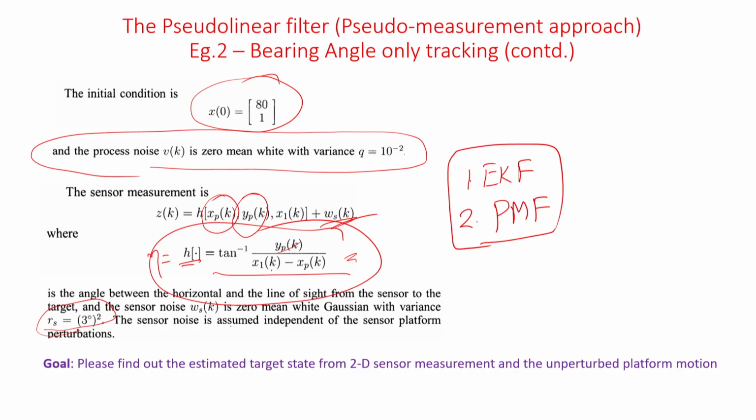If you had another equation, say eta dot, observability would have been more. What I am trying to tell again and again is that there is a direct connection to Kalman filter or EKF divergence or convergence, because EKF is an approximation method. It is a first order Taylor series approximation within the mean of a Gaussian random variable. It disregards the probabilistic spread of the system.